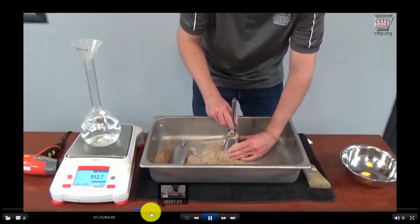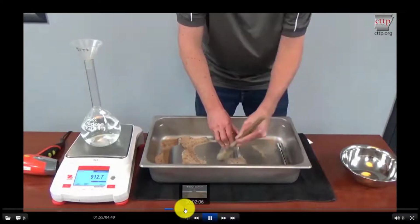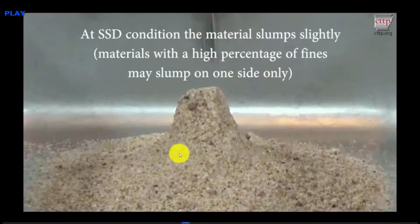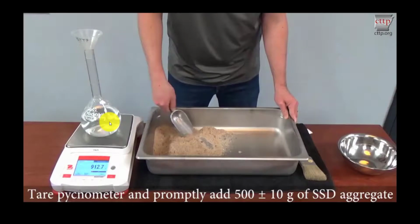After compaction, you will remove it. If it has retained the shape, it means it has got the SSD form. So this is an SSD form in which a few of the material has been detached and the cone is partially retained. So you will add the SSD form aggregates into the pycnometer.